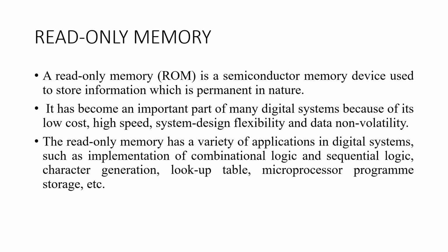It has become an important part of many digital systems because of its low cost, high speed, system design flexibility, and data non-volatility. The read-only memory has a variety of applications in digital systems, such as it is used to implement combinational logic as well as sequential logic. It is used to implement character generation. It is used to implement lookup tables in FPGA. It is used to implement microprocessor program storage, etc.